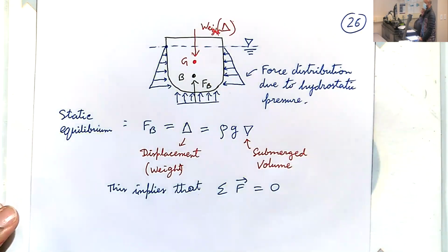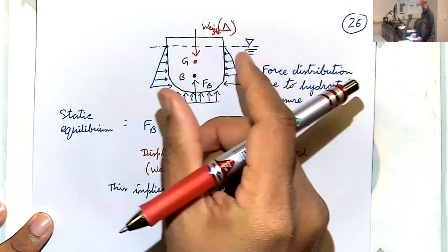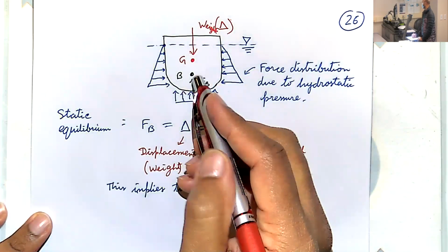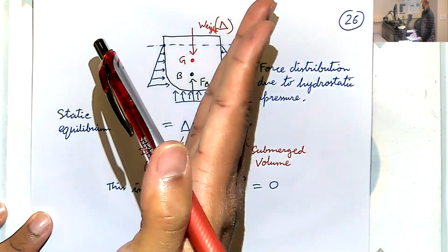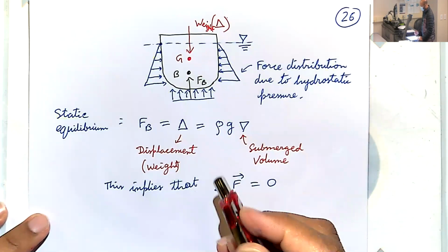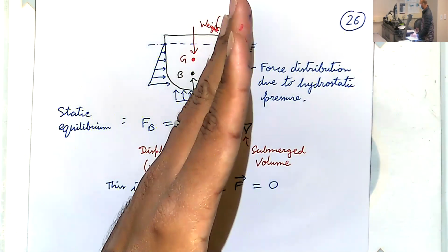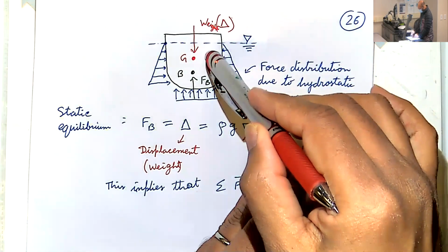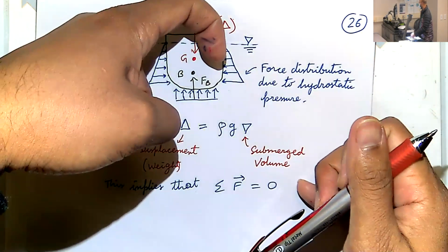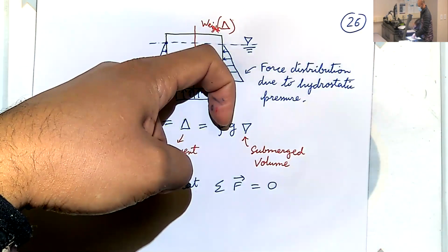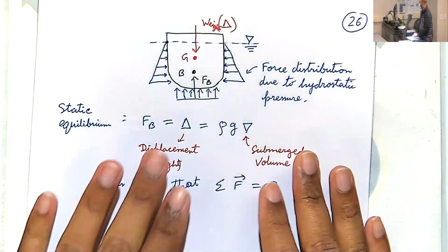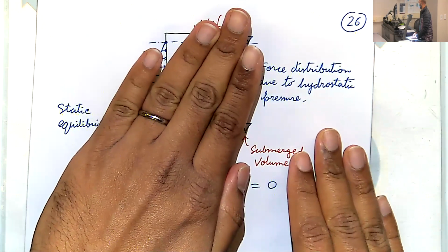So we know all of this intuitively. If you place a heavy weight on this side, the ship will heel a little bit clockwise. And it'll do so up until a point where everything becomes balanced again, okay? So what does that mean? It'll tilt until the new G and the B are in line again. So basically the weight and the buoyant force are balanced perfectly again. And at that point, it'll stop. So it'll tilt a bit and it'll stop.